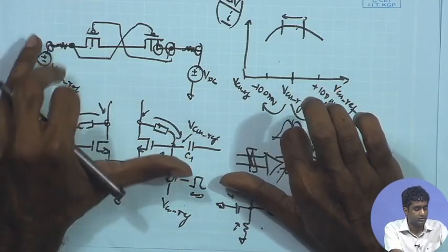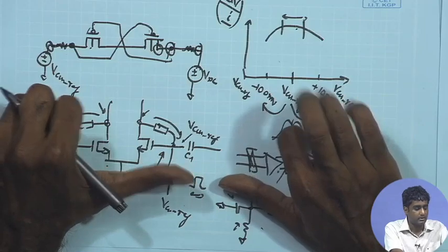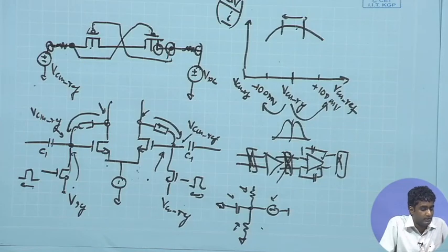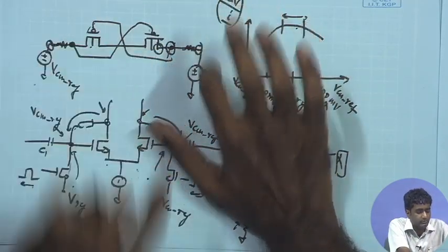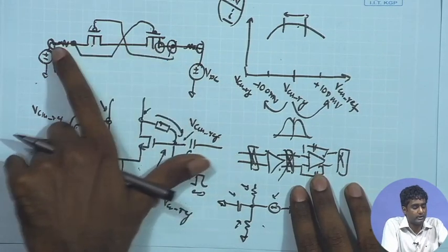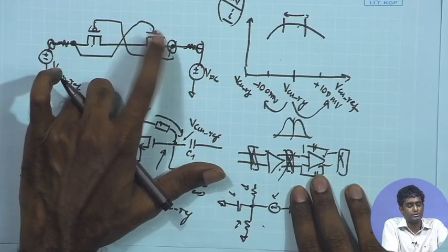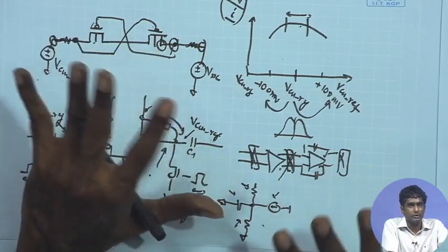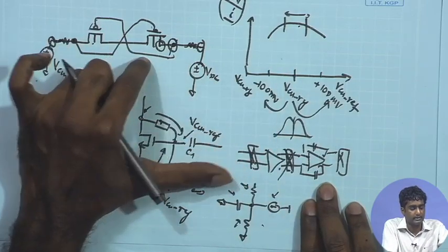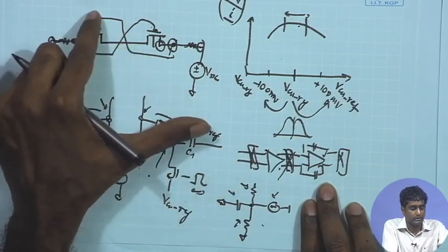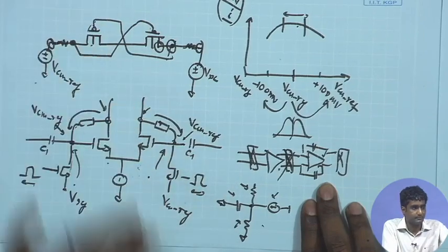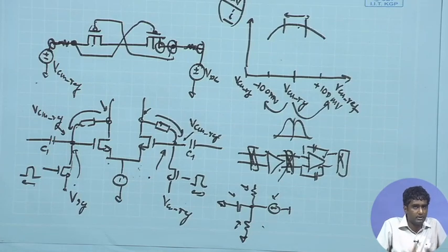Especially the gate to bulk leakage, and likewise the bulk to junction leakage, are not very significant. As the potential difference starts increasing, both of them will have more leakage, other leakage components coming into the picture. Here we are interested in source to drain current; other leakage components like junction to bulk leakage or gate to bulk leakage will destroy the characteristic that we are looking for. As the potential difference across the gate and the source, or gate and the bulk, increases, all those leakage components increase exponentially, because that is mainly based on tunneling effects.